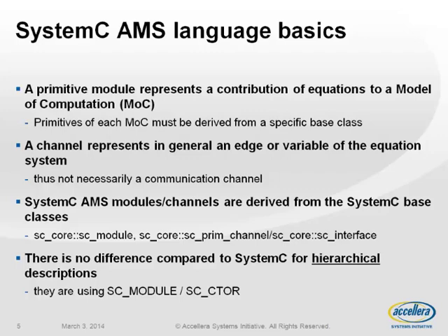Nevertheless, all SystemC AMS language elements, that means the modules and also the channels, the connections, are derived from the SystemC base classes. In this way, we have the same behavior for connecting modules and for building hierarchy of modules. If you compose a system in a hierarchical way, then we use the same methods like we have in SystemC. That means we have to create SC modules with a SystemC constructor, and we have to instantiate and bind the modules the same way like in SystemC.